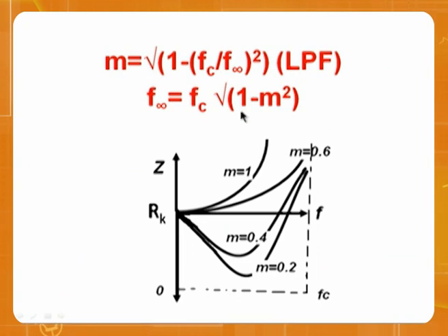So when you say composite filter, the meaning is this. Look at here, the impedances, how they are going. You look at here, constant K, M is equal to 1. This impedance is changing very badly. When you say M is equal to 0.6, impedance is slowly rising. So M is equal to 0.6 is better than M is equal to 1. That means M is equal to 0.6, it means half section. Half section is better than constant K.